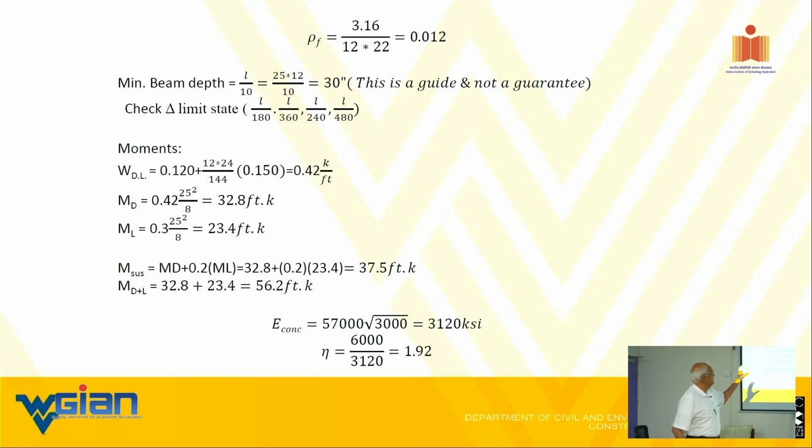Actually, that is a misnomer. Talking about the deflection as a function of span is a kind of misnomer. It should be really related to the curvature. What is that? That's essentially the slope equation. L/delta is what we are saying is 180 or 480. That's L/delta. What is L/delta? It's a slope issue. That is not right, because I can have a tremendous curvature and have a failure, but still meet the L/delta of 480. You see what I say? Never mind, I don't want to get there.